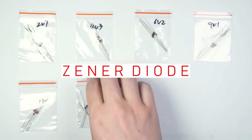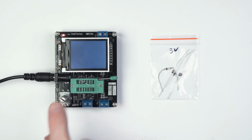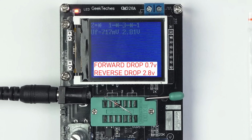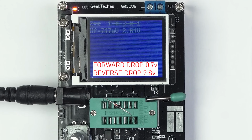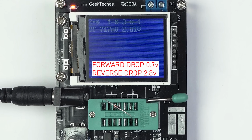A Zener diode looks very similar to a regular diode. Sometimes they can even be confused. When forward biased, the Zener diode works pretty much the same way as a regular diode, demonstrating a voltage drop of about 0.7 volts. But if you apply voltage in reverse polarity, that is, reverse bias the Zener diode, it will also conduct electric current. And its voltage drop in reverse mode can range from 1 to several tens of volts, depending on the reverse breakdown voltage rating of the actual part.